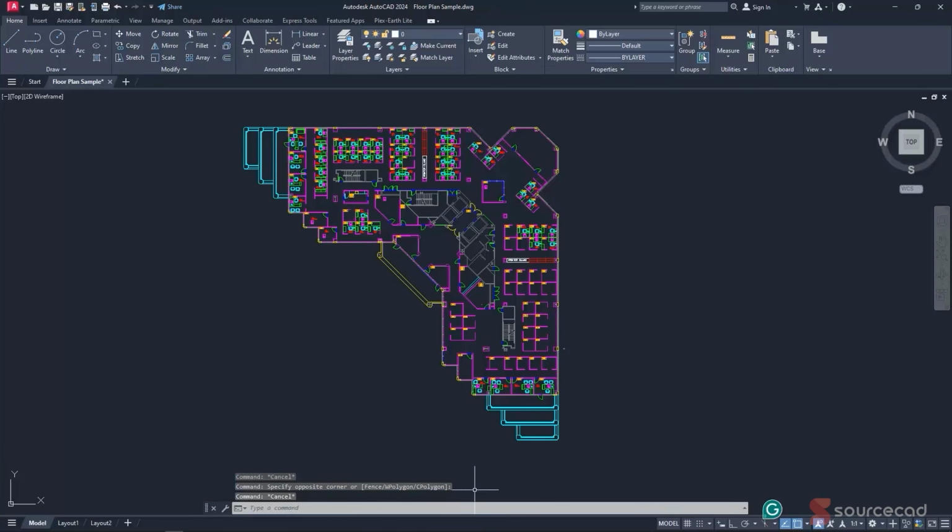Not only that, but you can actually see the dynamic movement when you're working with your design. So make sure you toggle it on. And how do you toggle it on? When it is blue, it means it's active. When it's grayed out, it means it's off. Make sure that it's on. Not only that, we have other commands such as the grid view. If you want to see your grid, just press on this once and now we can see our grids. But I don't prefer seeing them, so I'll just simply toggle them off.